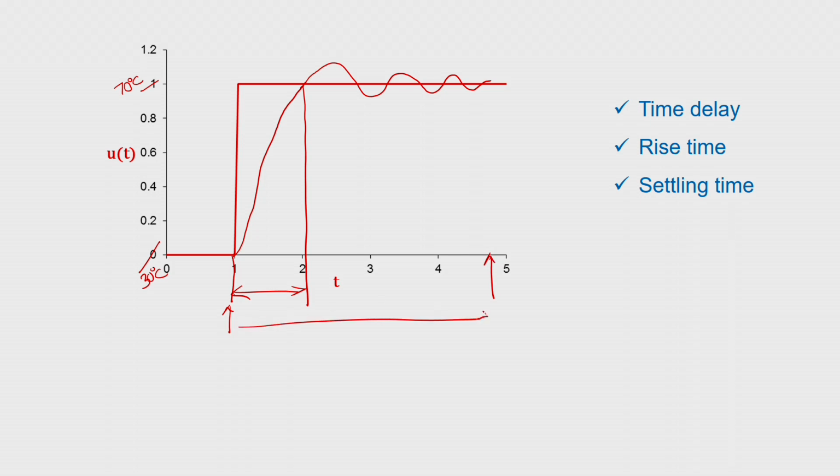So this entire thing refers to the time delay of the measurement system. Rise time refers to this particular one, that is, the initial time when you are imposing the signal and the first point when it attains the output signal value, but it is not staying constant at the output signal value, rather it is oscillating around a bit.